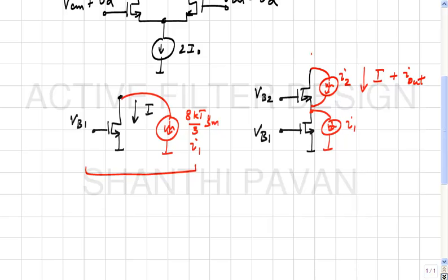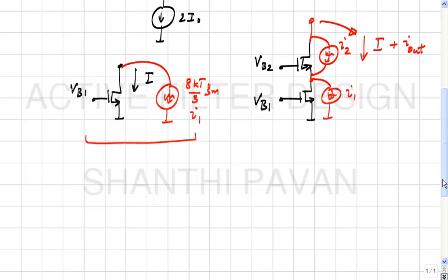Okay, it is clear. So to find I out in terms of I1 and I2, what will I do? How would I figure out I out in terms of I1 and I2? People, come on. Okay, first we assume that both these sources are deterministic. Find the transfer function from I1 to I out and I2 to I out, and then add their spectral densities, because I1 and I2 will be uncorrelated. Okay, so what do you think the easiest way of doing this is? To use superposition, right?